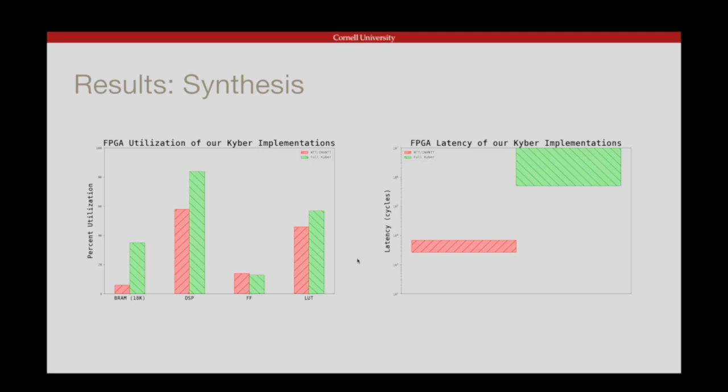The first of these is that there is unusually high DSP usage overall compared to previous labs. This is due to the multiplication involved in Montgomery conversion, which is a key part of making arbitrary moduli fast in cryptography to achieve the necessary modular arithmetic. In Montgomery form, performing a modulus over one value can be converted to performing a modulus over an arbitrary other value. By picking this other value to be a power of 2, moduli and division in hardware can become fast. However, converting in and out of Montgomery form requires a multiplication step. This is also a key factor in why the overall algorithm can't be as optimized as one might hope. Specifically for NTT, we had to avoid unrolling a large loop iteration as there weren't enough multipliers.